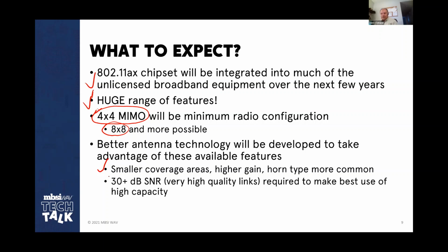I can use 33 or 45 degree antennas on it, and reach out my 3, 4, 5 miles, whatever it is, in unlicensed, and serve these customers at 256 QAM. Whereas today, with the technology I have, maybe the best I can do is 64 QAM or even 16 QAM. But we're going to see that become much more common as well.